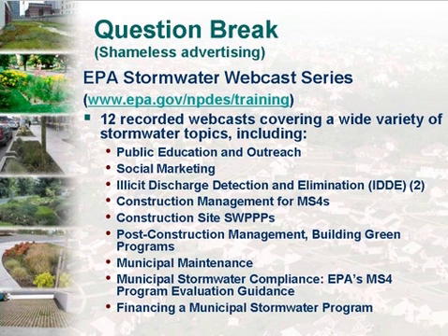And I think that was, at the time, a kind of a guess, basically. And I think as we're moving further and further into research into stormwater, maybe we're finding out that that's not necessarily the best performance metric to choose, because it's really only talking about pollutants. And I think we've emphasized today that we need to be concerned about volume reduction. And, of course, that simple percentage, which this idea seems to imply, is not necessarily the best way of measuring the output into a stream, a river, a lake, or coastal water. We still have to be concerned about that total load that's going out there. So, again, you can get 80% off of a very dirty site and still be in violation of water quality standards. So we think that there's some better metrics out there.